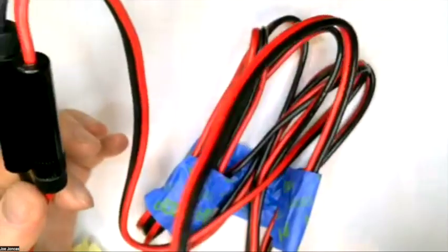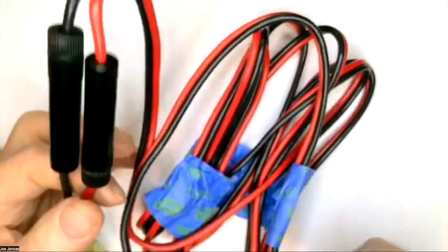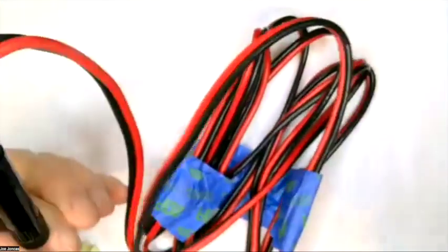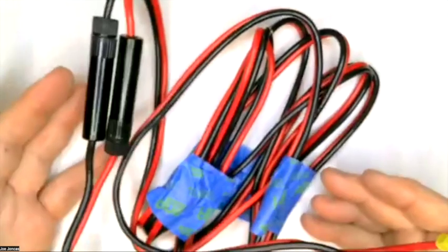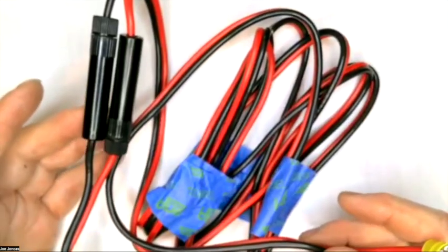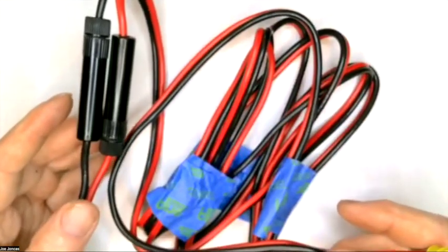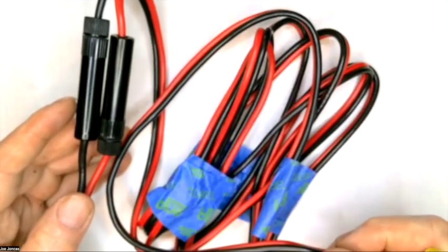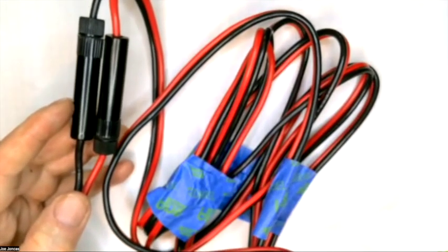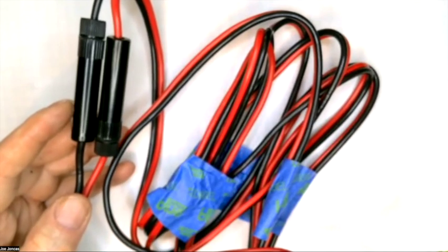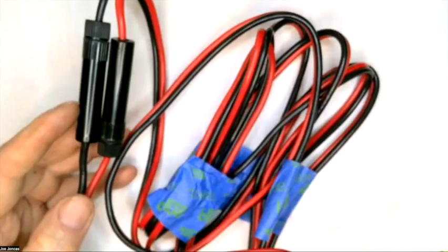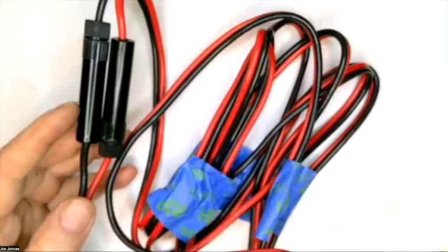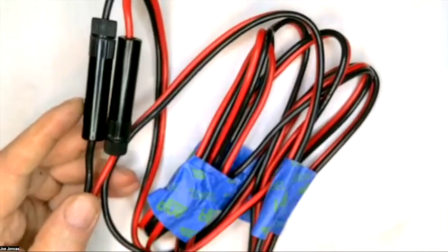the wire gets hot because it's a resistor. Normally this is number 12 wire, and from here to here I'm going to guess there might be 0.3 ohms, 0.5 ohms. But if you start going 0.5 ohms up and 0.5 ohms back, and you draw 20 amps through it, oops, I think I'm an order of magnitude out in that.